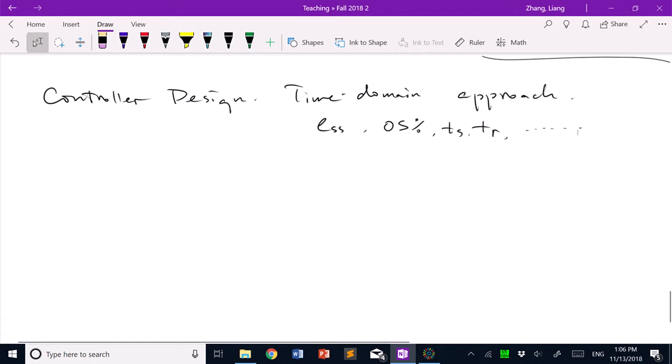In the next chapter, we're going to discuss how we can approach control design from the frequency domain, meaning we're going to look at the frequency response function, transfer function, and discuss how to do the control design. And we'll do this through examples throughout that chapter. Now, as far as controllers are concerned, we actually discussed this in the previous chapter. We're looking at the commonly used types of controllers: P control, proportional control, PI, PD, and PID.